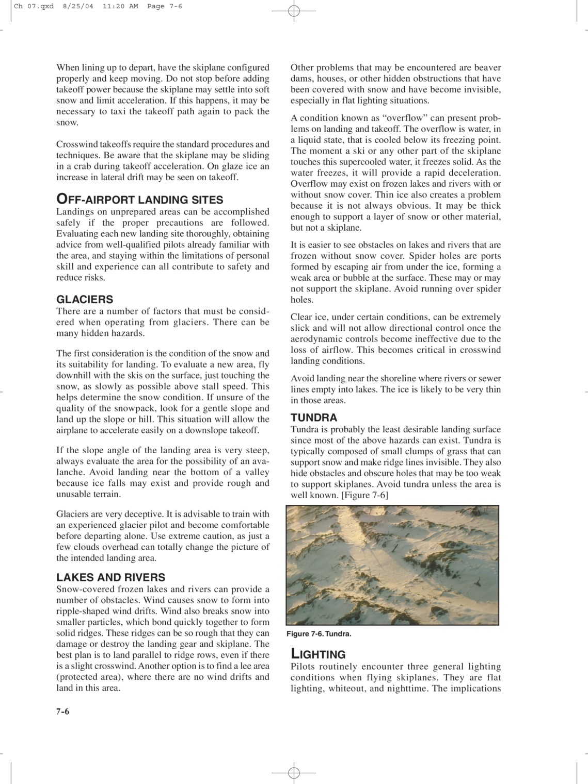Glaciers are very deceptive. It is advisable to train with an experienced glacier pilot and become comfortable before departing alone. Use extreme caution, as just a few clouds overhead can totally change the picture of the intended landing area.